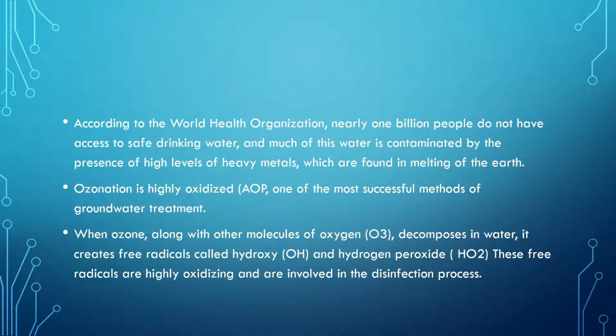When ozone, along with other molecules of oxygen, decomposes in water, it creates free radicals called hydroxyl and hydrogen peroxide. These free radicals are highly oxidizing and are involved in the disinfection process.